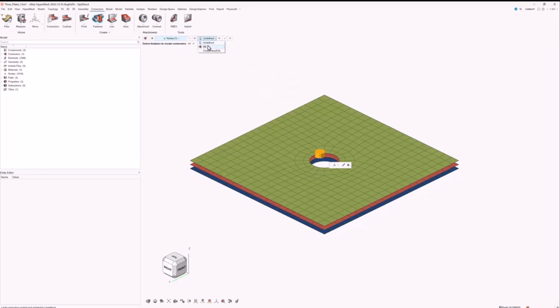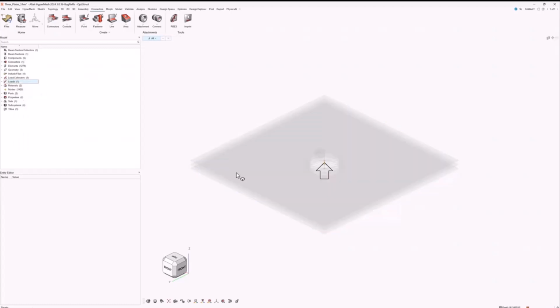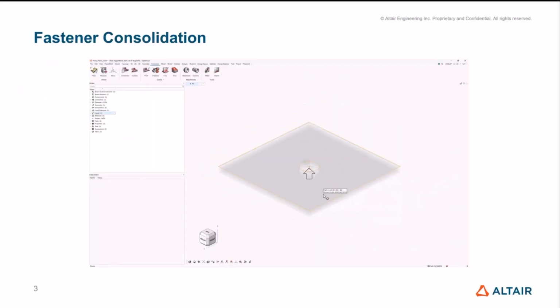Select a node, obviously, same workflow as before. Generate the realization, same workflow as before. In this case, now the diameter is explicitly taken from the realization, so it generates an M6, even though the hole is significantly larger, and we've got pretension generated on the top beam of the realization. Now, if I jump